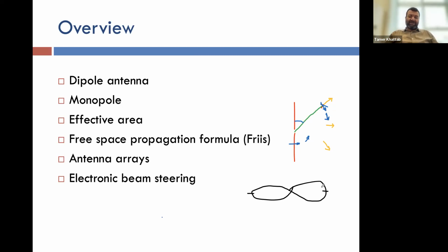Okay, that was one property of the antenna. So you have a radiation pattern that tells us, in different locations of space, how the power is generally distributed for that antenna in terms of concentrating it in certain directions and less in other directions. And then if we want to know, in the direction of maximum, how do we compare to an antenna which is not focusing the power? Then we use a measure called the directivity of the antenna.